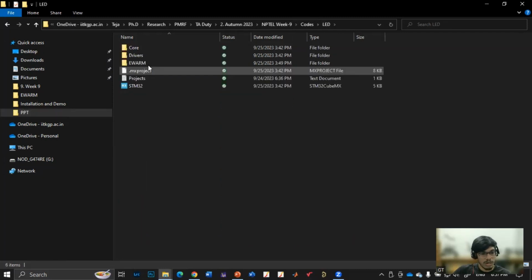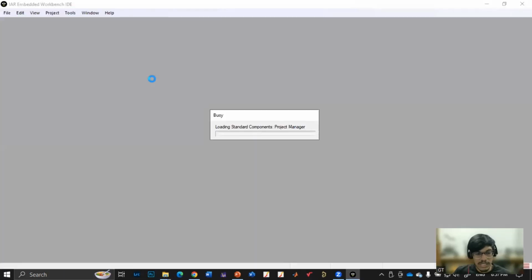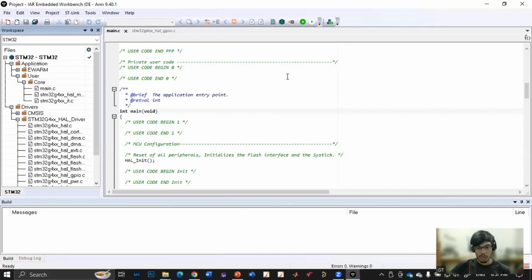So this is the LED code, EWARM. It is just the copy and paste of the code I have implemented here as well. So now I'll turn off the screen and I will show how that LED is working. I'll stop sharing, and now my video is visible. I'll unblur, and first I'll run my code. You remember that 1000, right? 1000 means 1000 milliseconds, which means 1 second. So toggling happens at the rate of 1 second. Now I'm running the code, and I'll show you.